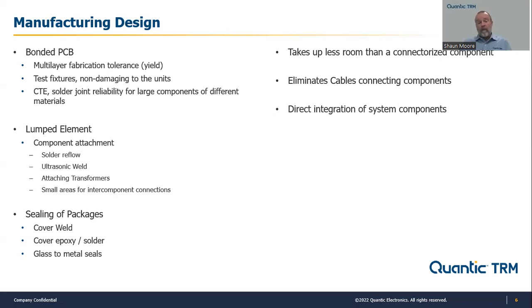Again, the sealing operations, depending on the package, are the same sort of idea. You want to close up the package. The requirements can be different because now, if we're going through a direct solder operation at the next higher assembly, do these have to be able to go through there and be sealed against things like degreasers for soldering operations at the next higher assembly? In which case the level of sealing may be very different and may have to actually be more stringent or better than a separate connectorized component.